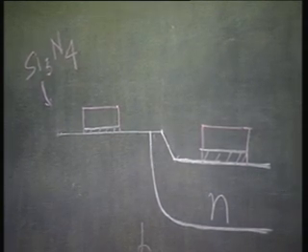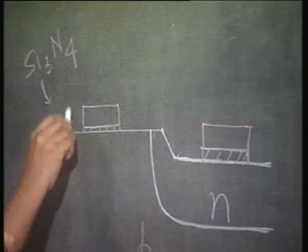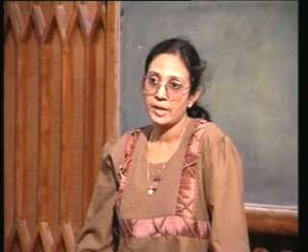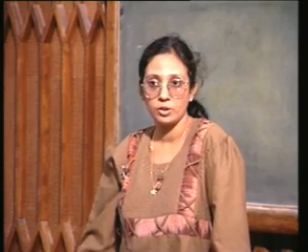Okay. But before carrying out LOCOS, what you can do is, you can do the boron implantation for the channel stop, right. Remember we mentioned this yesterday, that underneath the field oxide the substrate doping must be raised, so that the parasitic MOSFET does not get inadvertently turned on.